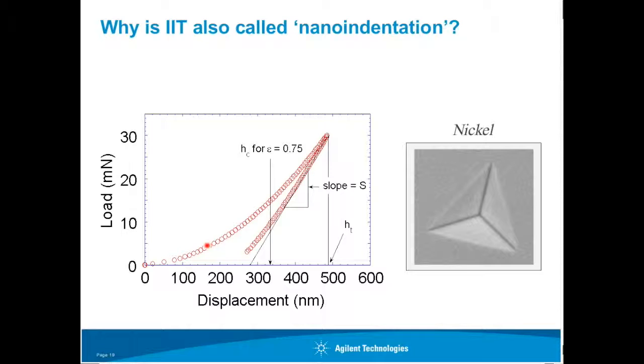What you'd have to do is look at the details of a Martin's hardness test or whatever other kind of test that you wanted to do. And if you wanted to mimic that with an instrumented indentation test, what you'd have to do is mimic the test conditions of the original as closely as possible. But with instrumented indentation in general, you have a wide latitude in the kind of test that you perform. You know, you have a wide latitude in what kind of indenter geometry you select. You have a wide latitude in the way that you impose force and measure displacement and so forth.